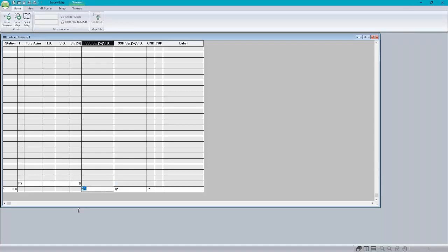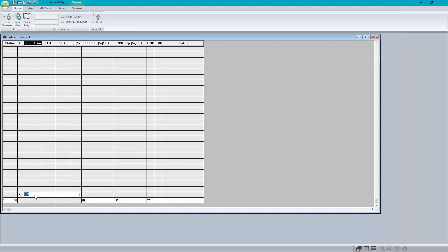So a typical P-line traverse has azimuth, distance, slope, and side shots. Now, if I wanted to pick up information about the ground where I've already got lidar data, then the side shots aren't necessary. So let me open a P-line that I created just a little while ago.